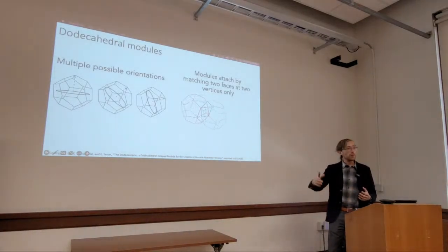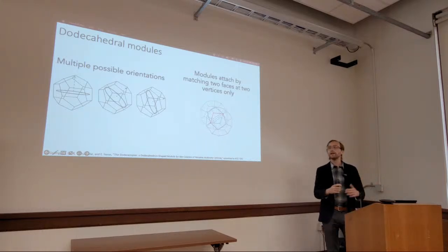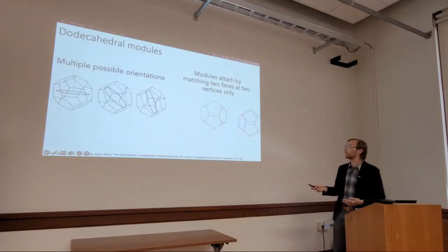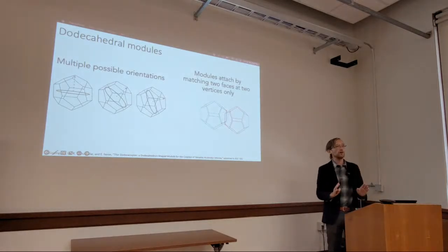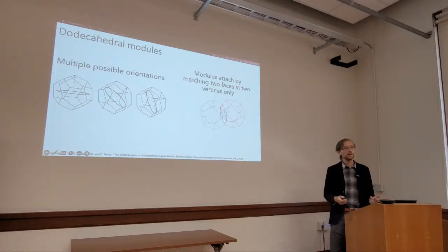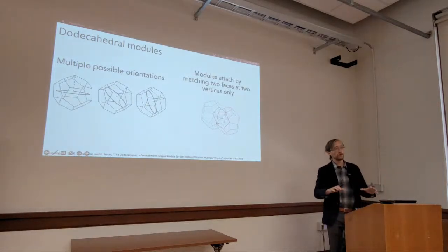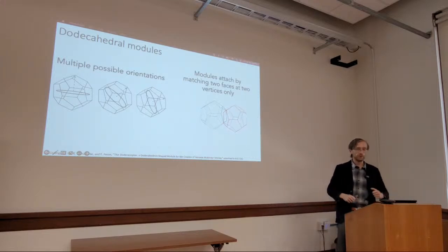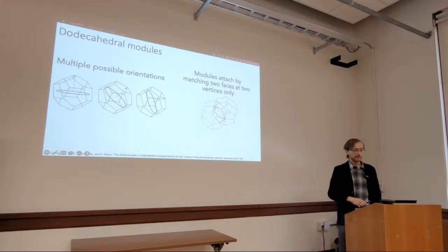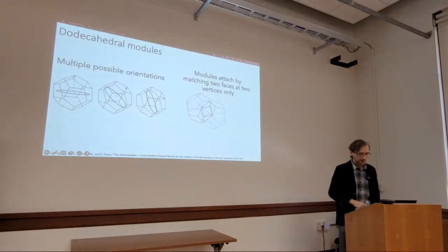we won't be able to connect a 3rd module to both of the first 2 modules, because the dihedral angle of the regular dodecahedron, which is the angle between 2 faces, would have to be 120 degrees to do that, and it's not the case. It's actually lower than that. But with this connection mechanism, we can connect a 3rd module, let's say on top, that will be connected to the 2 other modules. And so we have basically a triangle made of dodecahedra, if that makes sense. And so we can create more structurally efficient structures and recreate a lot of existing rotorcraft configurations.